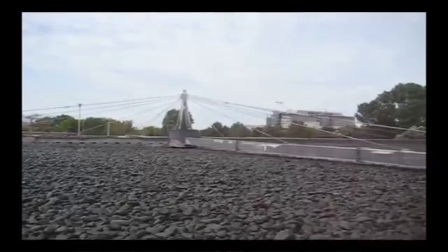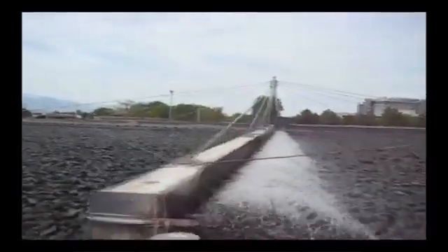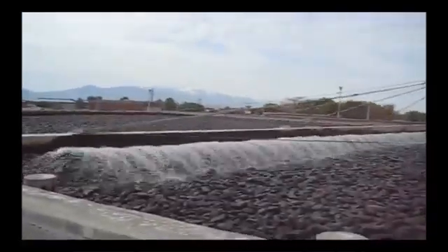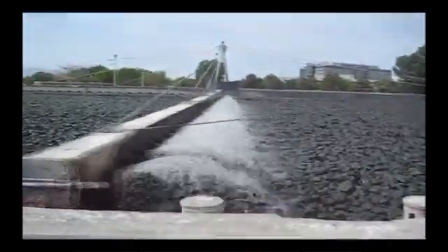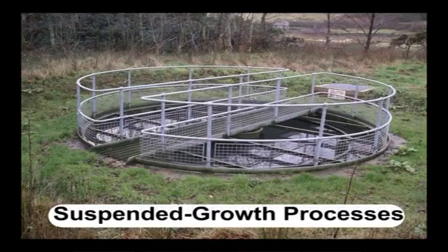and packed bed reactors. These systems are known as attached growth processes, where pre-settled wastewater is continuously trickled or sprayed over the filter. In contrast, systems in which microorganisms are sustained in a liquid are known as suspended growth processes. The trickling filter is one of the most common attached cell processes.